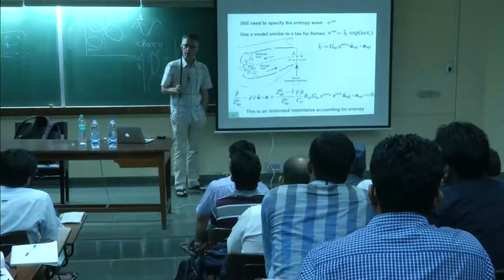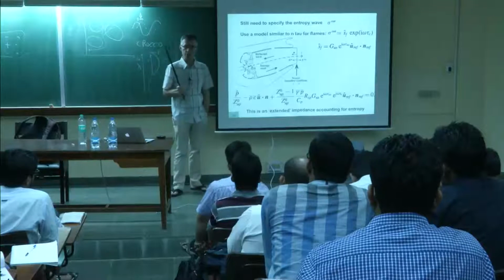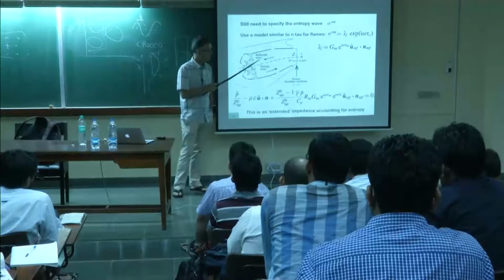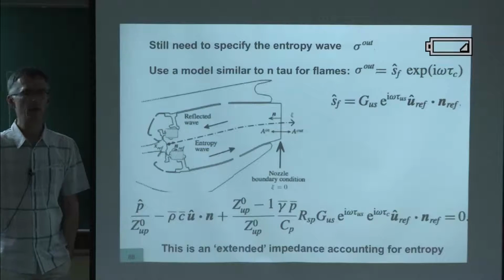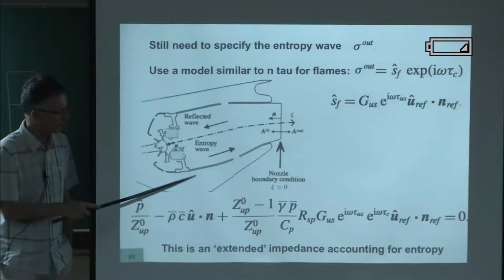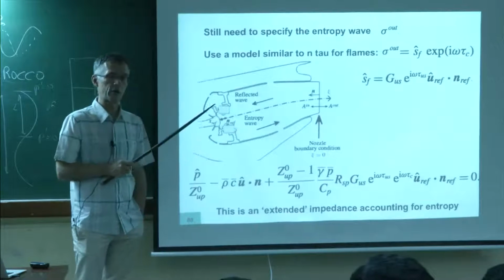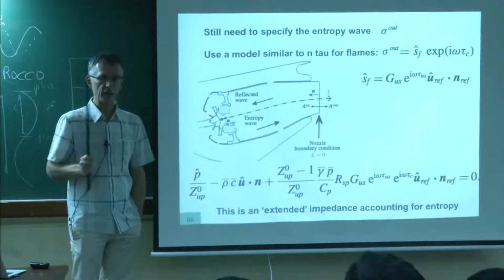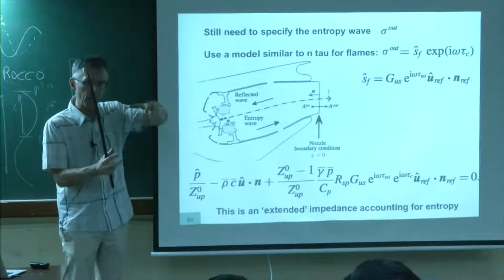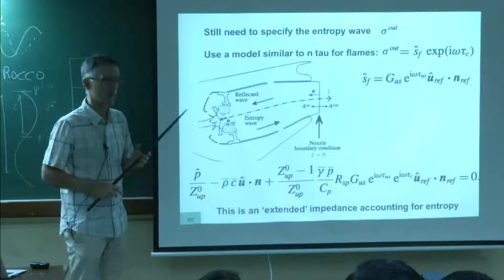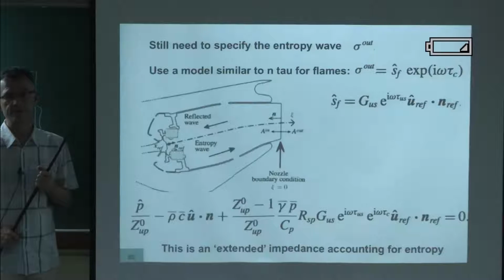It's important to say also that these transverse modes are not discussed often, but for example, Siemens or Alstom, when they have a transverse mode here, it kills the engine very rapidly. This is why they need to add Helmholtz resonators here. It's the same for Alstom. So transverse modes are also a big problem, but normally in gas turbines they're able to control it. In rocket engines, the problem is that there's no space to put Helmholtz resonators, so it is a major problem, yeah. It is a major problem. It's not a solved one.